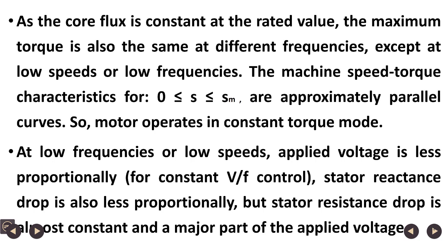At low frequencies or low speeds, applied voltage is proportionally less for constant V by F control. Stator reactance is also proportionally less, because reactance is proportional to frequency, but stator resistance drop is almost constant and a major part of the applied voltage.